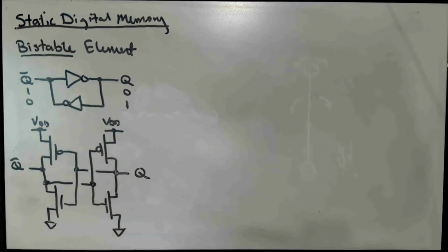So this is the simplest memory element. The problem is that we don't have any way of setting the state. If the state starts out 0, 1, then it's in a 0 state, and if it starts out at 1, 0, it's in the 1 state. But how do we actually get the circuit in that state to begin with?